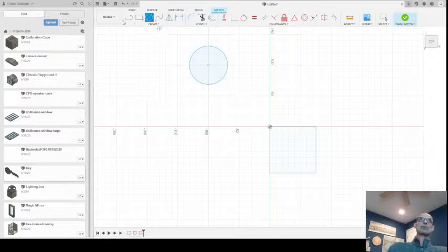And like I was saying before, it typically has to do with some kind of circle or curve. And here we have a circle and a line. The tangent places the edge of this circle on this line and forces it to be on this line, no matter where it is on this line, whether it's even part of the line that's visible or not, because this ray, this line, if you will, extends in either direction, kind of to infinity.